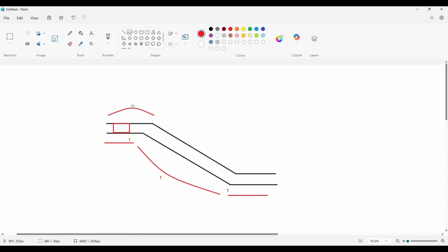So tension will be like this. Please understand this. Okay, so the tension zone will be something like this. So we provide the reinforcement on top. All right, so please keep this in mind whenever I'm talking about reinforcement: how does the reinforcement behave in the staircase region? Generally, if I have a bottom rebar going here, the bottom rebar will go all the way to the top over here.